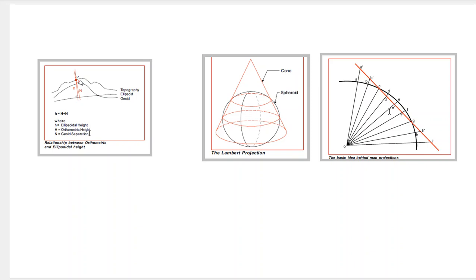So once again, the geoidal model will be part of a coordinate system, and in this case we'll have a state plane, which is a Lambert projection. So we're going to project from the ellipsoid to a mapping plane, and then attach the geoidal model to convert our elevations. And there are several different geoidal models, so it's important to get a geoidal model that matches another surveyor.